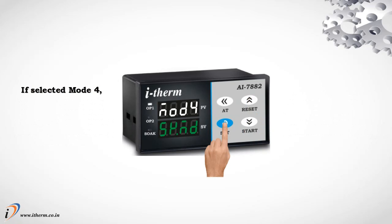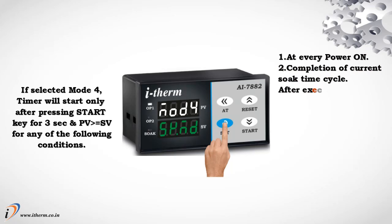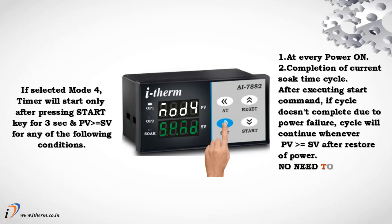If selected mode 4, timer will start only after pressing start key for 3 seconds and process value is greater than and equal to set point value for any of the following conditions. 1. At every power on. 2. Completion of current soak time cycle. After executing start command, if cycle doesn't complete due to power failure, cycle will continue whenever process value is greater than and equal to set point value after restore of power. No need to press start key.